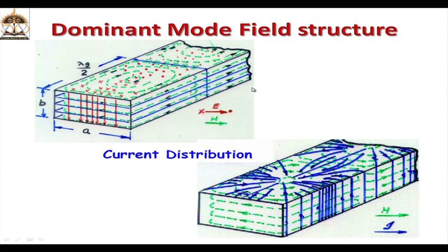are measured. We have already discussed in an earlier NPTEL lecture how to measure impedance, how to find fields etc., and you can see that lecture. There we use a slotted waveguide, in which we have a slot cut at the middle, that we can do because of this dominant mode, it does not have any current here.